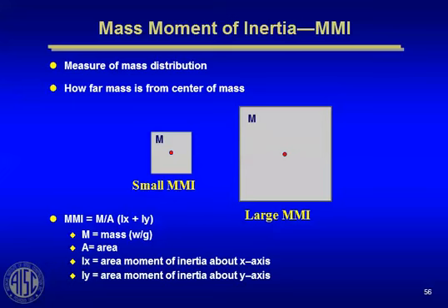You generally want torsion to be the third mode. You want the first mode to be a translational mode in one direction, the second mode of the building to be translational in the other direction. The third mode is the one you want to be torsion, not the first mode or the second mode. If you design a building and the first mode of vibration is a torsional mode, you probably have a torsionally flexible building that you should stiffen in torsion.